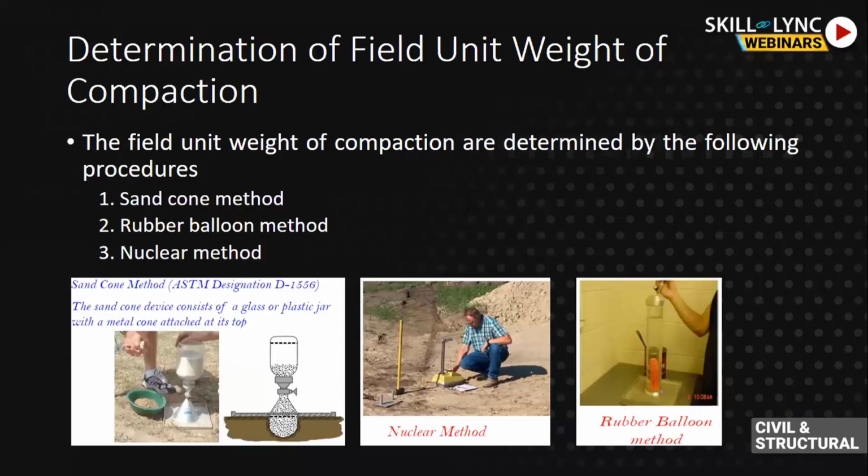The disadvantages of the sand cone method are that there are many steps, a large area is required to conduct this test in the field, it takes time, and it will stop all other activities. It will halt the equipment while the test is being done, and it is tempting to accept flukes, which happen most of the time in practice. The disadvantage of the balloon method is that it is slow. There is a chance of balloon breakage, and it can become awkward in the field.